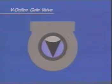This design is called a multi-orifice gate valve. The valve closure consists of a fixed plate and a moving plate. Flow is controlled by changing the alignment of long, narrow orifices in the two members. These valves provide good control characteristics for gas, liquid, and steam services. Another adaptation of the basic gate valve is the V-orifice gate.